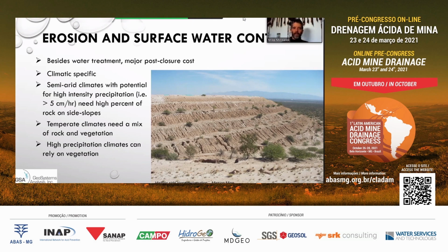The main reason is that in arid systems, the vegetation is not thick enough to control the surface water flow and to reduce the flow rates. In some high precipitation climates, you can get 100% vegetation cover, like in Papua. So if you can get that 100% vegetation cover, you've virtually eliminated or minimized the amount of erosion, because the raindrop impact is almost nothing at this point.